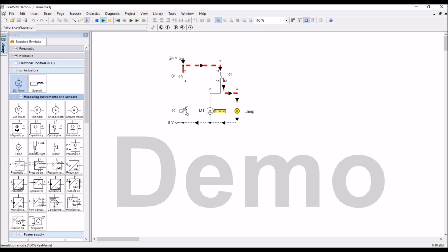When coil is energized, open contact becomes close, close contact becomes open, which belong to that coil. Okay, the contacts will get changed over when its coil is energized. That is the main function. So I hope you understood the function of relay. Application, we'll have a discussion.